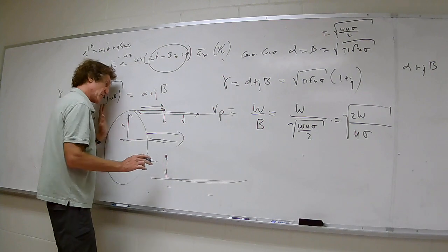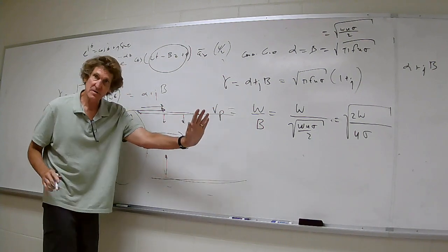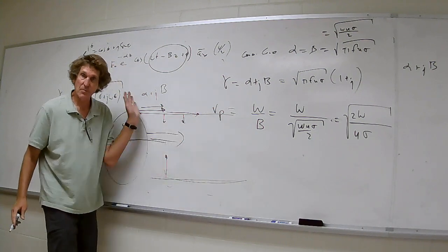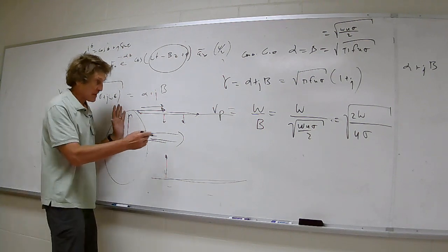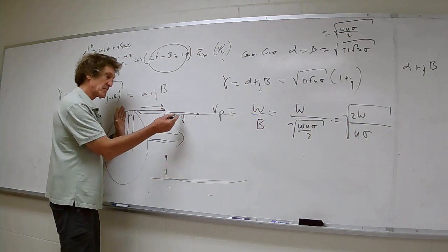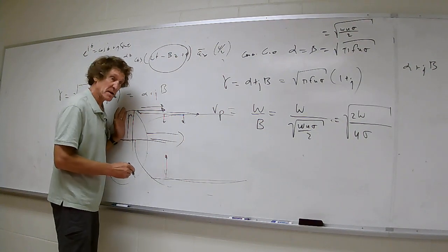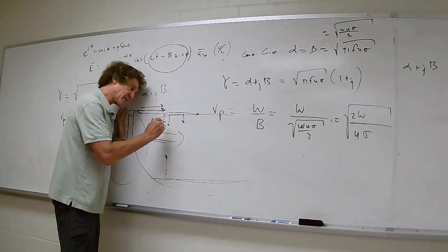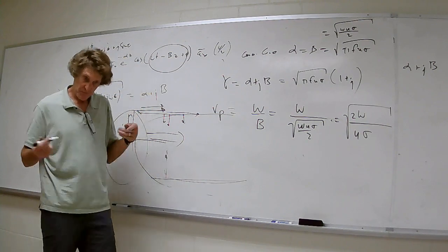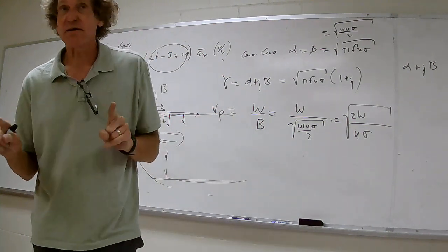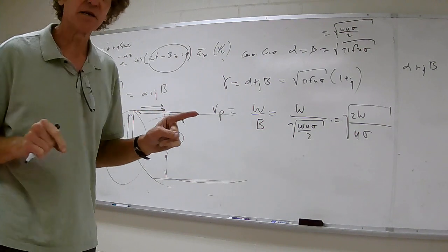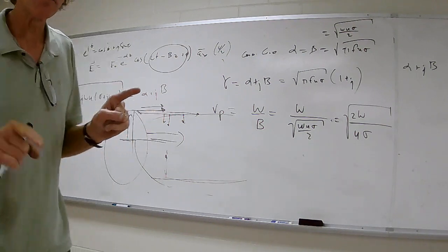Think of this, the electric field is shoving the current down this way. Really, it's a voltage, but it's going to develop an electric field on the surface. The actual magnitude of the electric field as you go into there will short out like crazy. Alpha is going to be the same as beta. It won't go deep, but the rate that it's flowing towards the center of that wire, you could say the wave velocity there, is going to be that phase velocity. It can be much, much less than the speed of light.